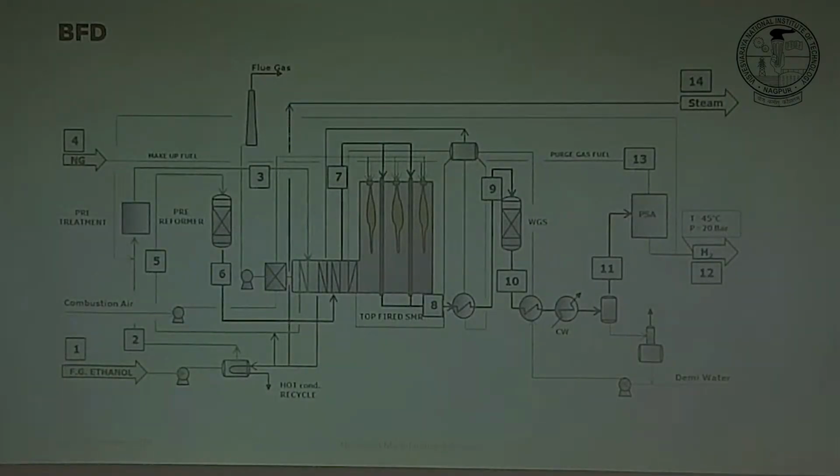Hot gas coming out at 850. There is steam generation here. That's the steam drum, the shift, what we also saw in our block diagram. Further cooling, preheating the feed, right? And final cooling, PSA system, and then you have your hydrogen product, right?